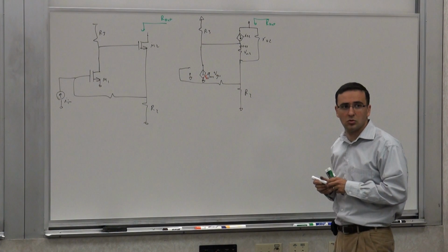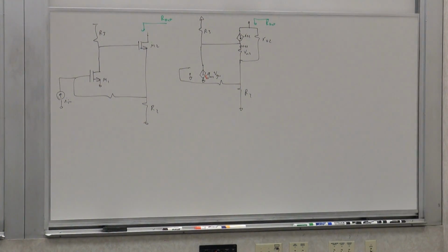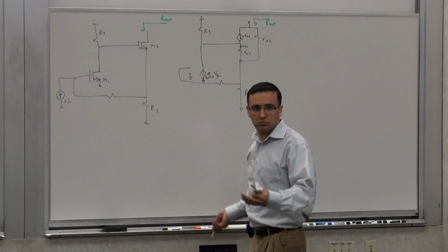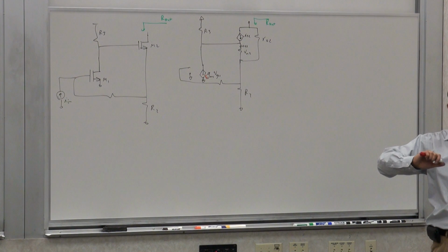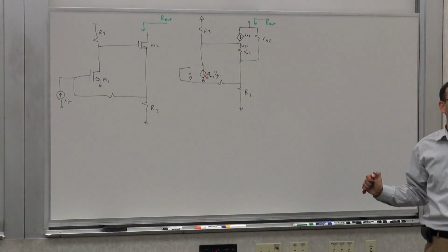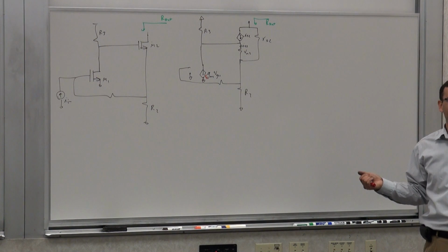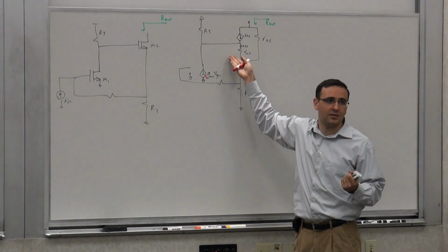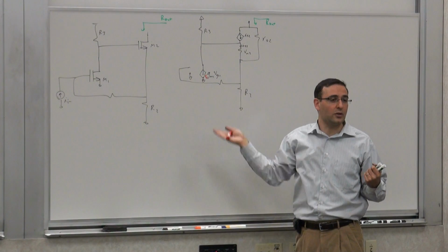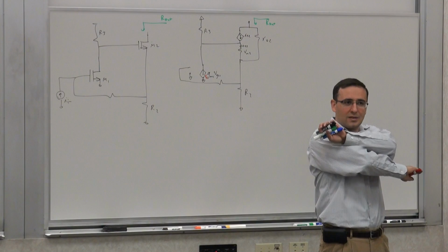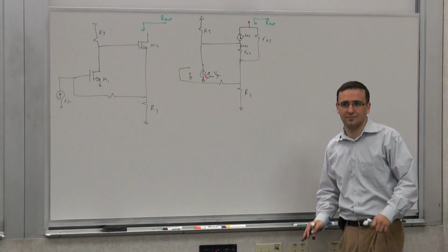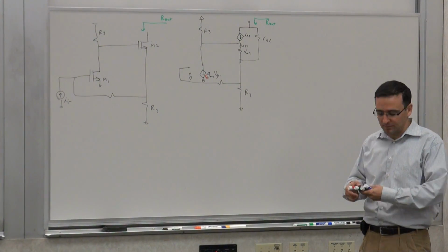Is there any reason that you choose this one? This is straight in the feedback path, the forward path, not the feed forward path. So we could use the other one. There's nothing magical about it. You can use anything, it just makes it easier. Ideally, I want something that completely kills the feedback, because that makes my calculation of R out 0 simple. If I don't kill the feedback, then R out 0 is going to be as complex as calculating R out. I just want to eliminate the feedback as much as I can, and make it as simple as possible.